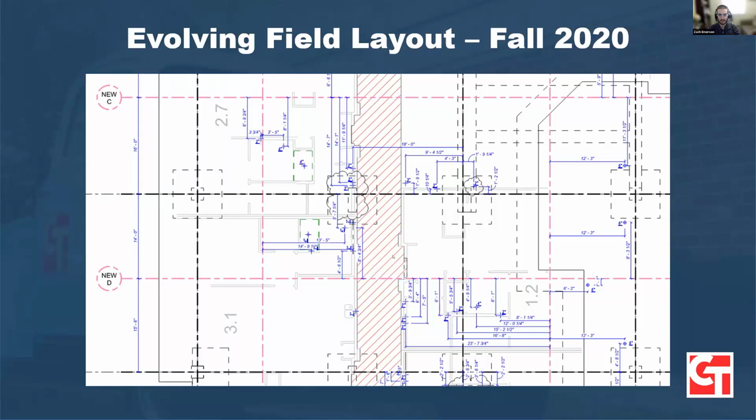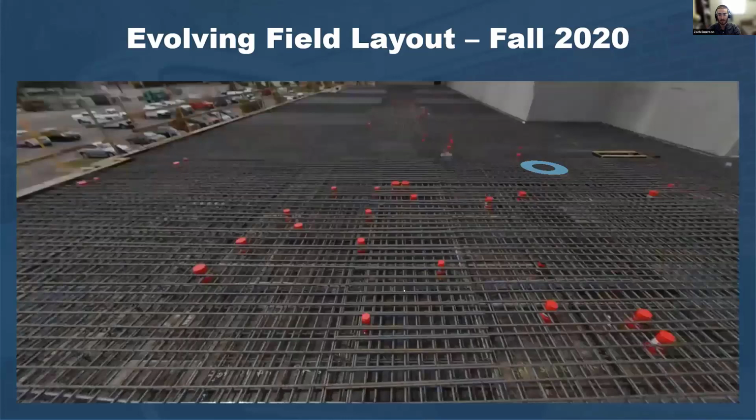In order for this process to start, you have to get your concrete form deck up, and almost as soon as that happens, you typically have rebar installation starting as well. The preferred approach is to get all of your sleeves in first, just because rebar can really take up a lot of space. And if you don't have your sleeves in the right location early enough, you've got to work around rebar that's already in place. It can just really get away from you.